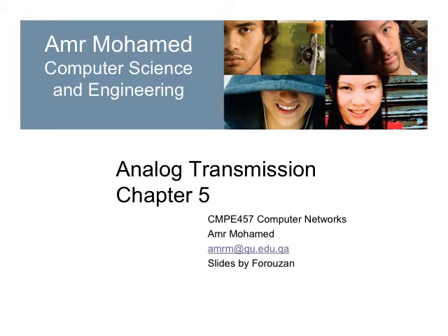And we said that this is good if the channel is a low-pass channel, which means that it passes the low frequency levels or the zero frequency component. Although we have found after that this still causes some trouble if I have line coding schemes like NRZI or some line coding schemes that have high power at the zero frequency component. This still causes a problem even for low pass channels.